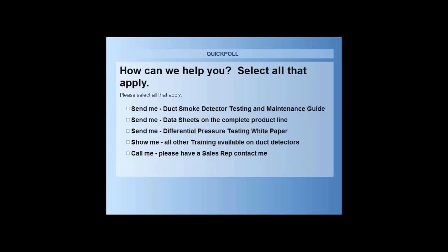When you see this condition, it means that the sensor has moved outside of its operation window. The detector either needs to be cleaned, which will usually put it back into the range it should be in, or if that does not work, the sensor head would need to be replaced in order to restore normal function to the detector.